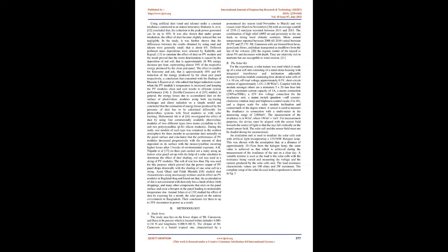[9] studied the effect of dust deposition on the front surface of the PV module by using 2 identical photovoltaic cells which were mounted on an angular movable stand and control board, and noted that the reduction in voltage generation by the unclean panel due to natural pollution deposition on the front of the panel for 3 months was about 3.8% compared with the clean panel, and 13.8% if compared with the voltage production by the panel when it has been cooled by water.